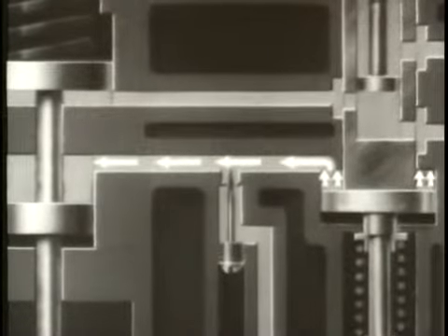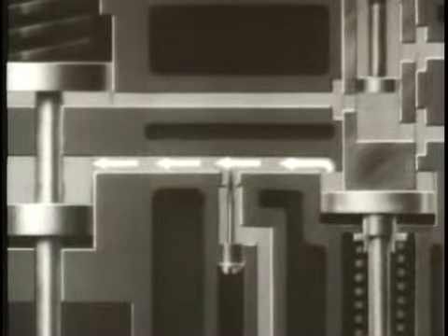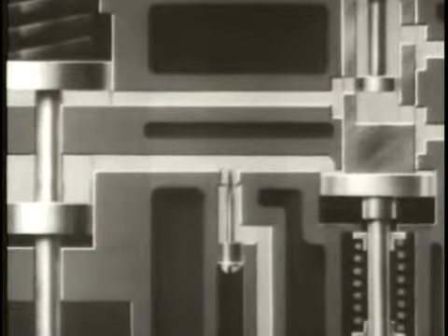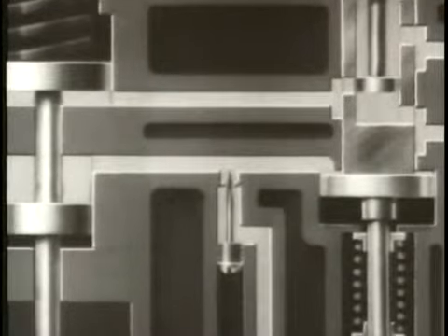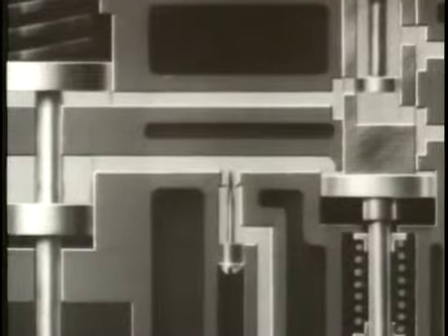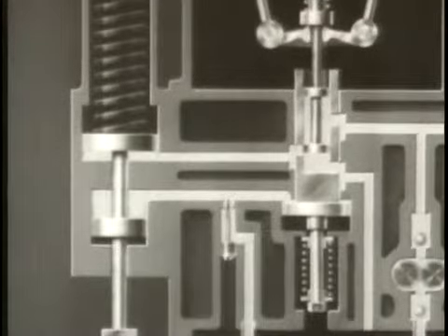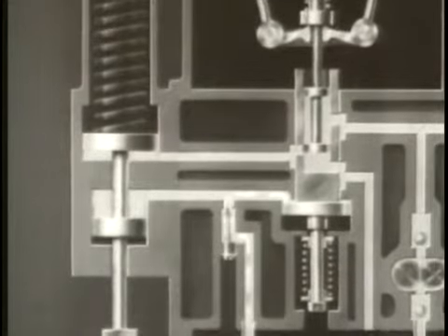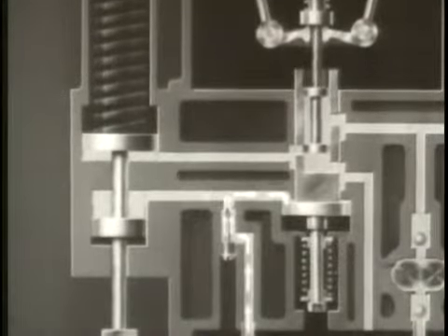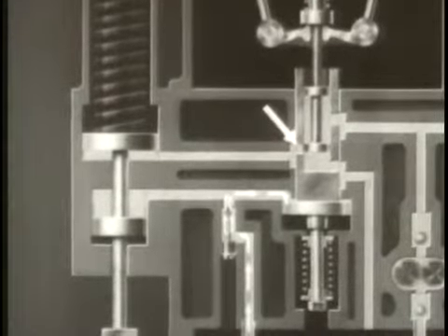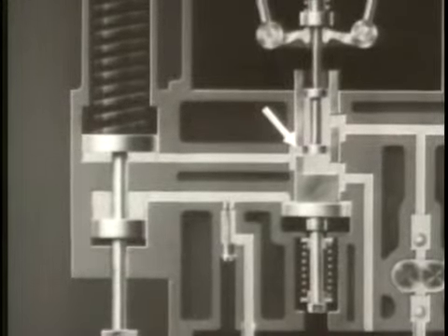This creates a suction above the receiving compensating plunger, which is part of the bushing. The bushing moves upward, closing the port to the power piston. Thus, the power piston is stopped, allowing no time for overcorrection. As the flyweights and pilot valve return to their central position, oil flowing through a needle valve allows the compensating spring to return the pilot valve bushing to its central position.